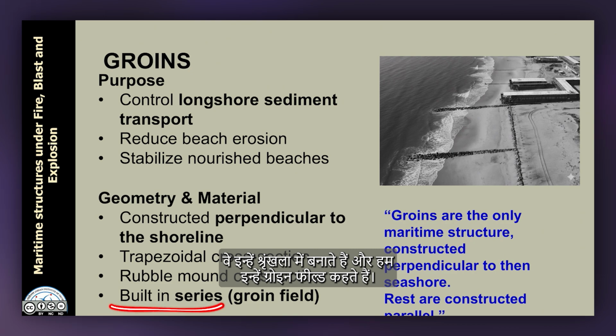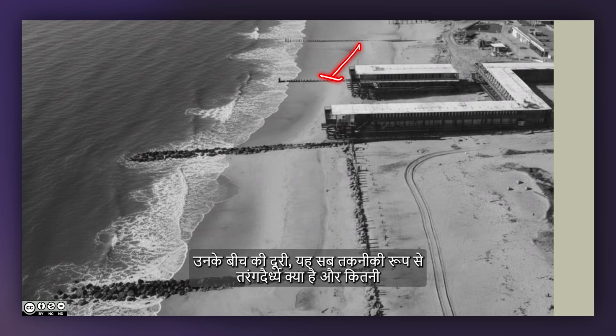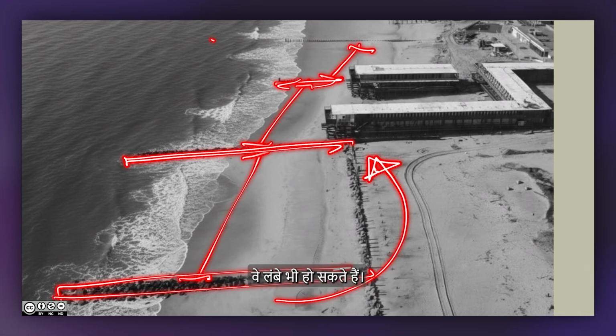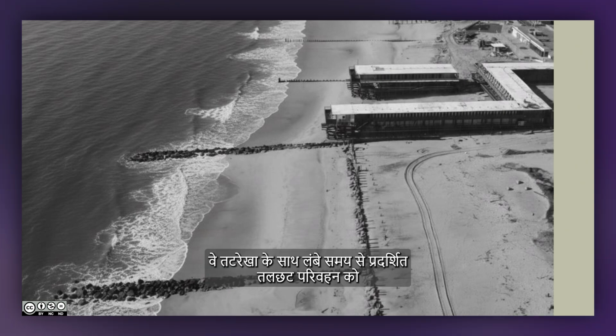They are built in series and we call them a groin field. As you see in this figure, there are many groins: 1, 2, 3, 4 and so on. The spacing between them depends on the wavelength and how much sediment transport can take place. The projection of these into the sea is also not uniform all the time. They can be longer, they can be shorter. They are all constructed perpendicular to the coastline and they are very effective in controlling the long shore sediment transport along the coastline.